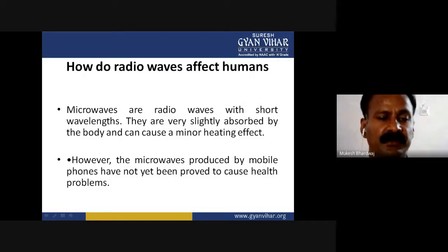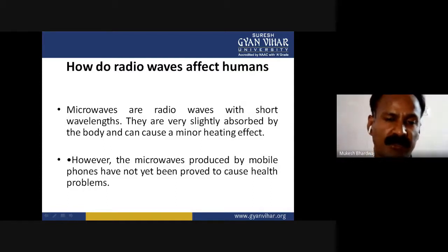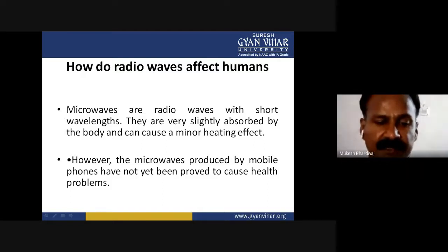Microwave power measurement uses bolometers and microwave power meters. A self-balancing bridge working on the principle of power substitution is commonly used. Microwave impedance measurement is done by measurement of reflection coefficient and voltage standing wave ratio. A slotted line and probe is the basic tool for these measurements. Network analyzers enable rapid impedance measurement over a broad frequency range.